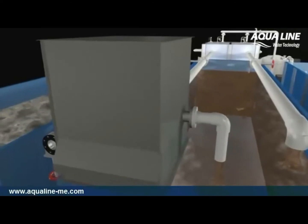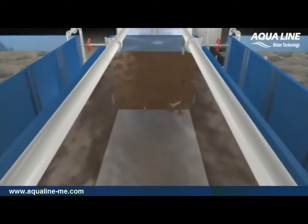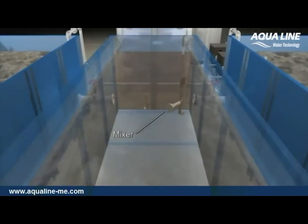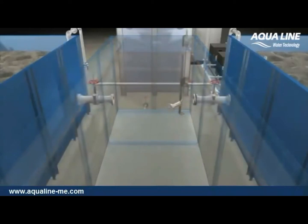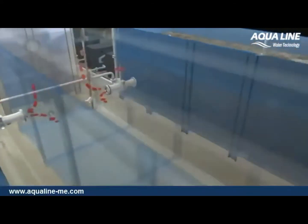Within the anoxic tank, a submersible mixer blends the screened wastewater with the mixed liquor, returning from the membrane filtration tanks at predetermined recycle rates to achieve the desired level of denitrification. In the absence of dissolved oxygen, nitrate is converted to nitrogen gas in the tank. The wastewater flows from the anoxic tank to the aeration tank.